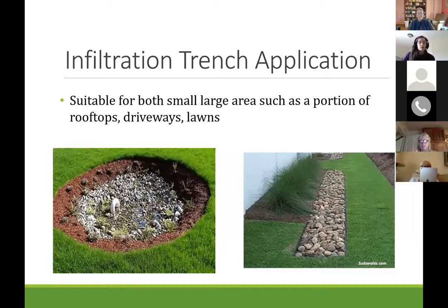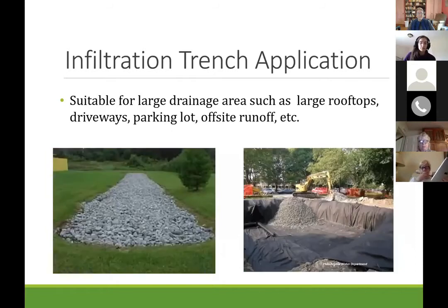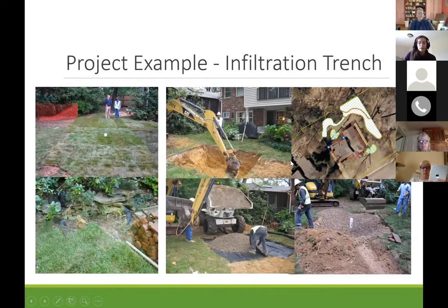Some of these can also be sized up to take a large volume. Of course, the costs increase as you get larger with these things. But here's an example of just how large they really can be, taking area from very large commercial settings, maybe parking lot runoff and other things like that. This is an example of an installation of an infiltration trench.